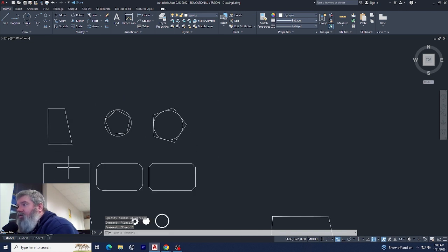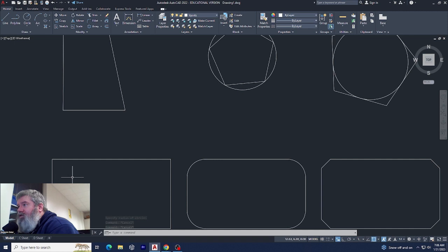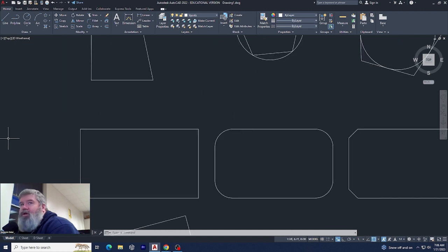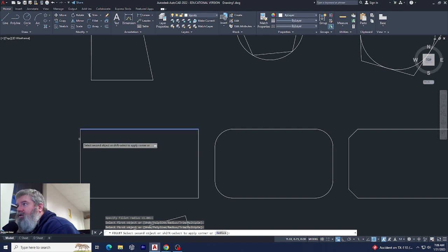I showed you rectangle. Now, what if you want this rectangle to have curved, rounded edges? I've talked about this with some of you, but this is called a fillet. It's right here, or you can type in FIL, and it comes up in your menu and say, I want the radius. So I hit R, enter, the radius of 1, enter. Then I select this object and this object, and it automatically curves it for me.